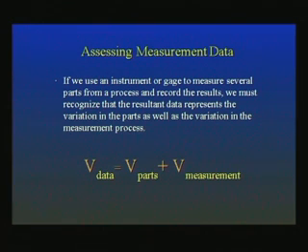If you are collecting data, part of that data could be because of the parts that you are using and part of it due to measurement errors. The variance that you see in the numbers you've collected from the instrument readings could be due to the true parts, because of the different parts you are using. When these parts are produced at different times, there may be some natural variation. Their heights are different, their thickness is different and so on. That is the natural variation, the part-to-part variation.